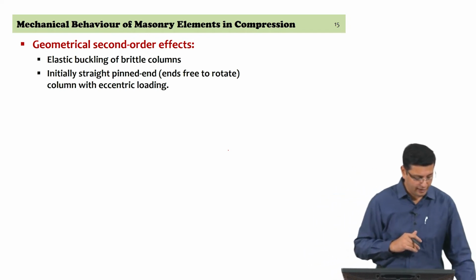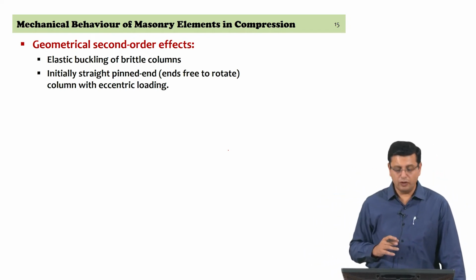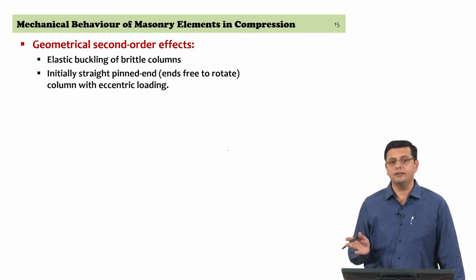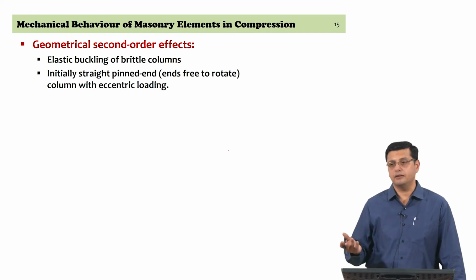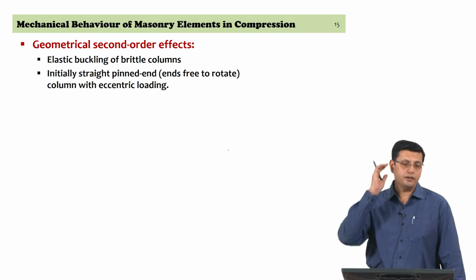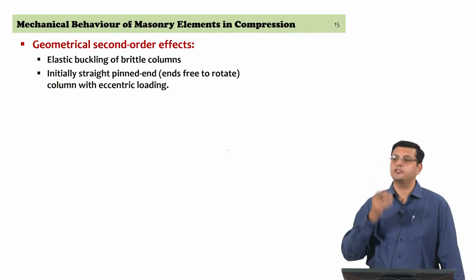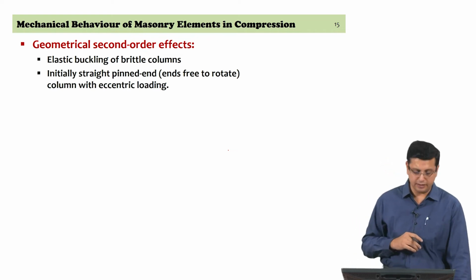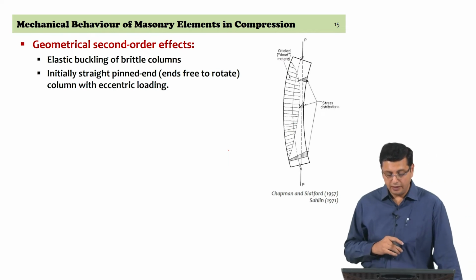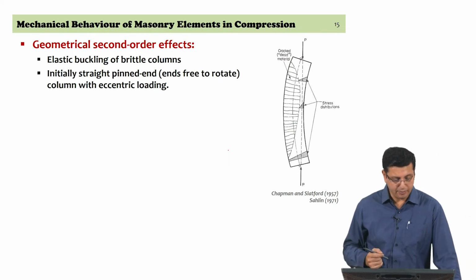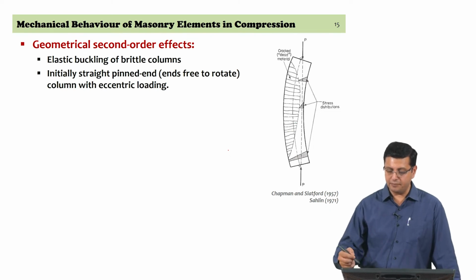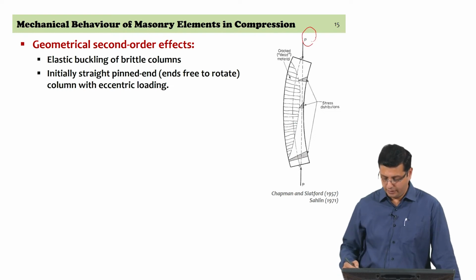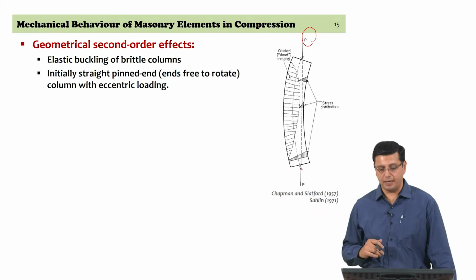from the engineering calculations themselves. So, we are looking at a wall that is initially straight, subjected to eccentric loading, and examine the deflections in the wall due to this eccentric loading, and see if those deflections are actually going to compromise the force capacity, the strength capacity of the wall itself. So, if this is the wall we are examining, we have an eccentricity of the load acting on it, P, and we assume that the eccentricity is the same at the top and the bottom.